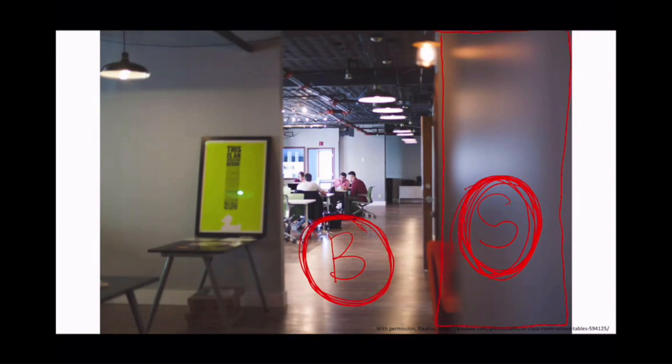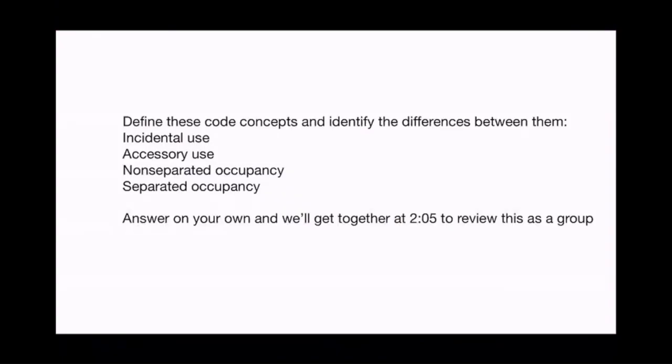If you have a situation where you have 2 different occupancies in mixed use, and one of them is bigger than 10%, or they have 2 different tenants, that's slightly more common. It's more common to choose the non-separated, because generally that little storage room or whatever won't push you over to the next higher level of non-combustibility and construction type. However, it's not uncommon that you would prefer to choose the separated occupancy.